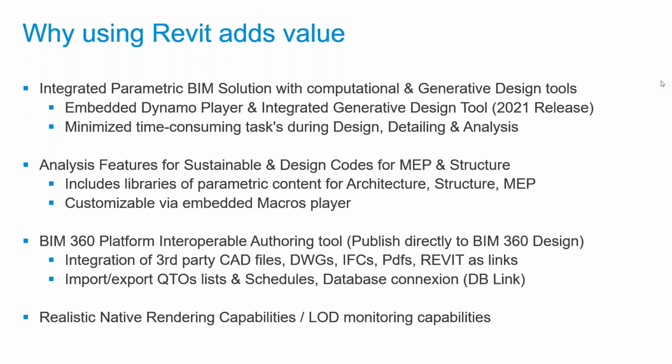There's also a Revit to Advanced Steel connector that was just released with the 2021 release. So if you do want to have a twin in Advanced Steel of your Revit structural model, which you're working with Robot with, say, you can do that, and the Advanced Steel model would be what you'd be uploading or XREFing into your Plant 3D model to generate orthos and such.